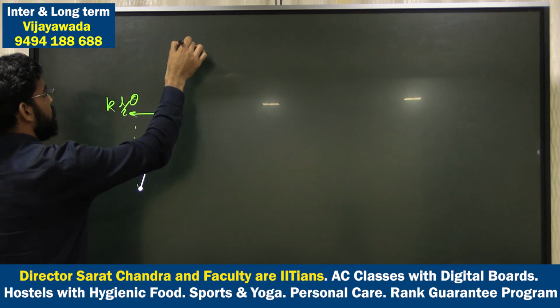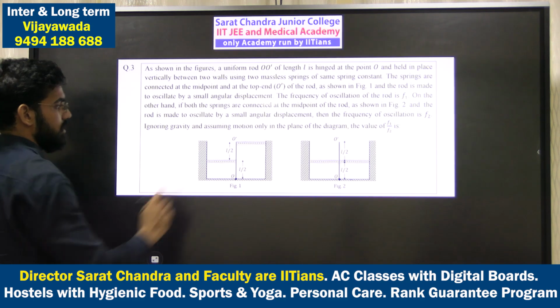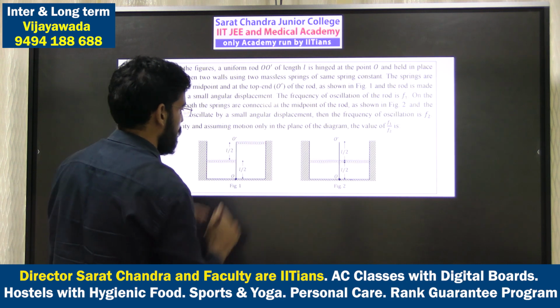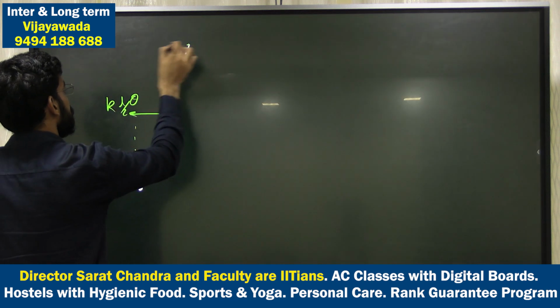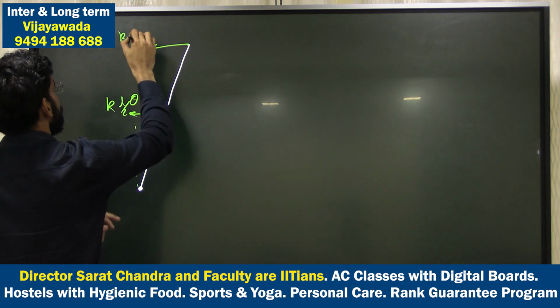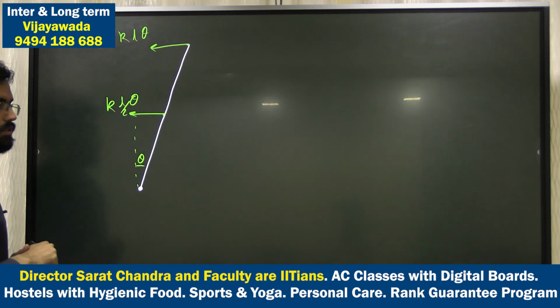And if you see by this point, if I move this rod this side, there will be a compression in this spring. Compression happened means the force will be in this direction. This will be K into L sine theta, so K L theta. These are the two forces, right?